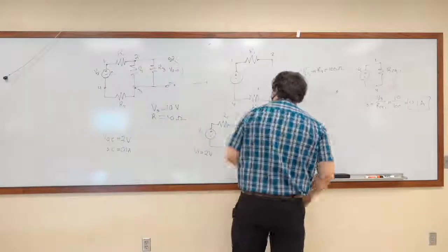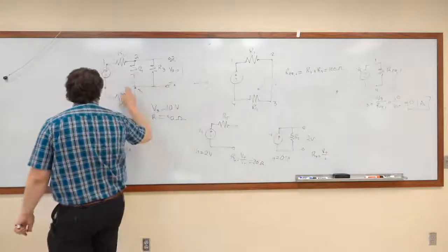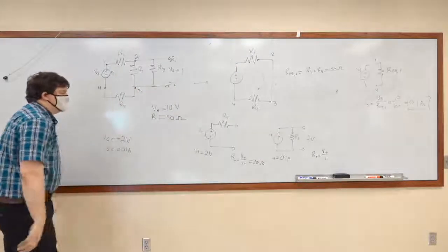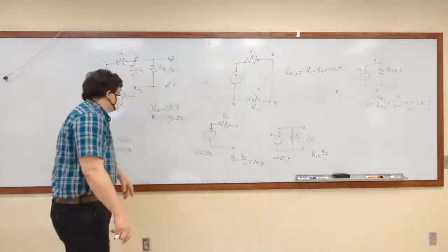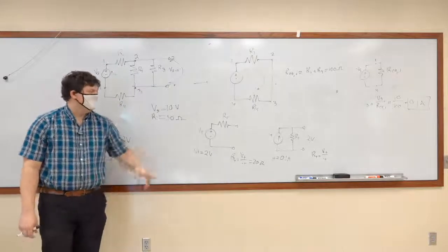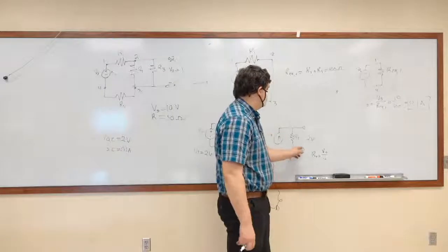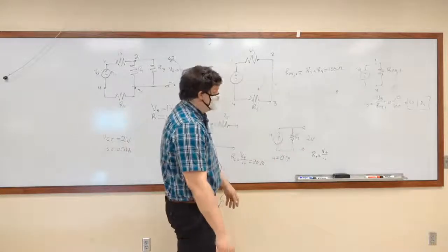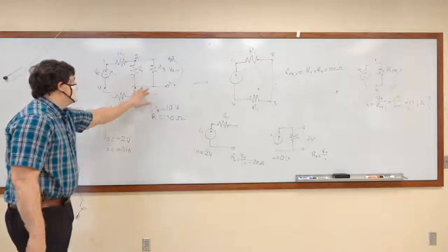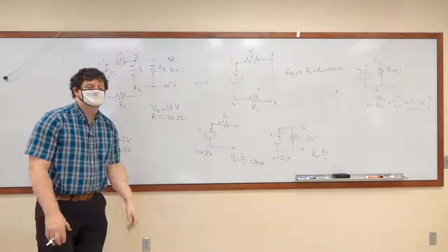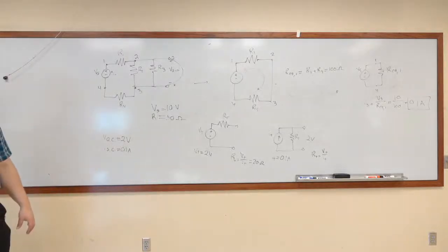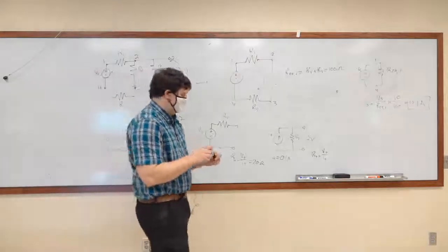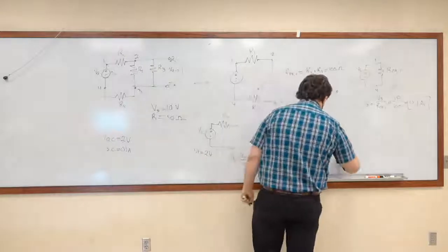Similarly with IT, the current that is flowing through R1, unless you're shorting this terminal, the current flowing through R1 is always going to be greater than the current flowing here to here. And the reason for that being that you have current that would be diverted to other branches in this circuit. So just a fun bit of math to play around with. Let's do one other quick example before we go. And I say quick because this is going to be really fast.